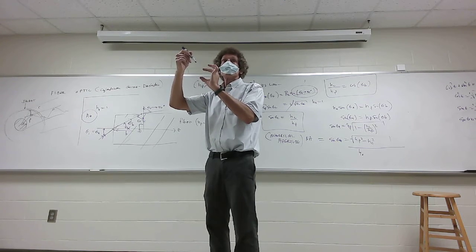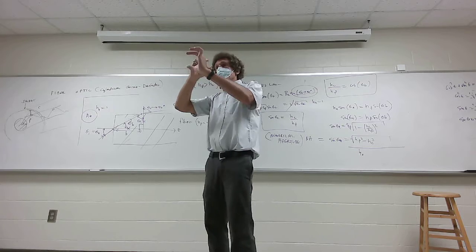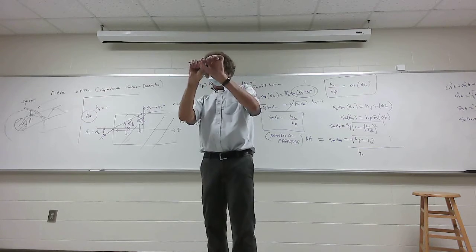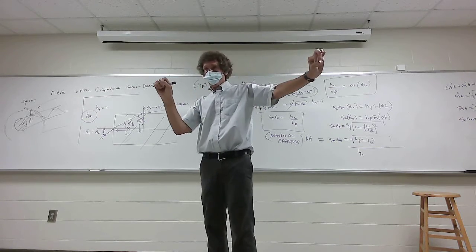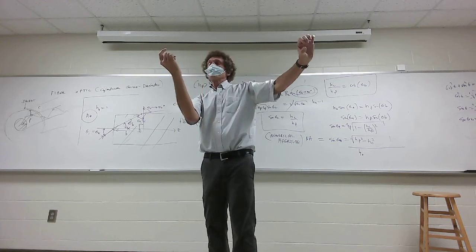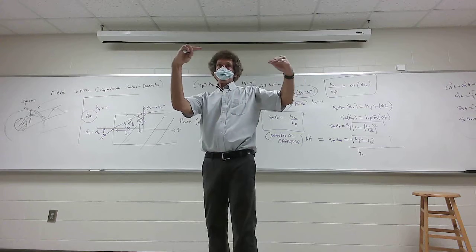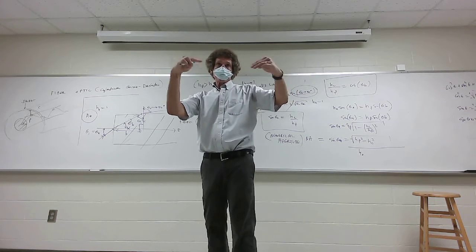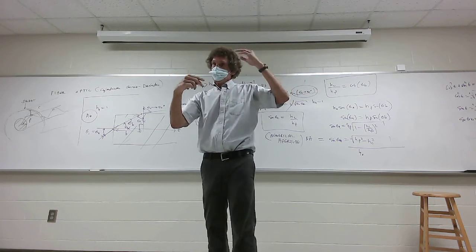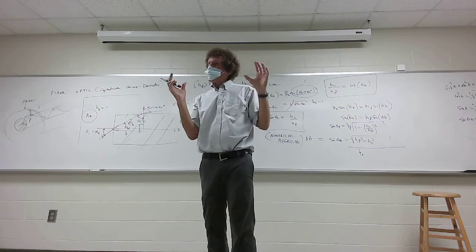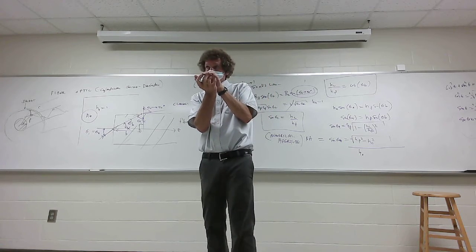It has to basically be the same stuff, and here's why. You have a long run of cable with a core of a certain material. If the thermal expansions aren't the same, then the material will actually move and shear apart as there are temperature changes. Remember this. So they try to make it as close to the same material as possible.